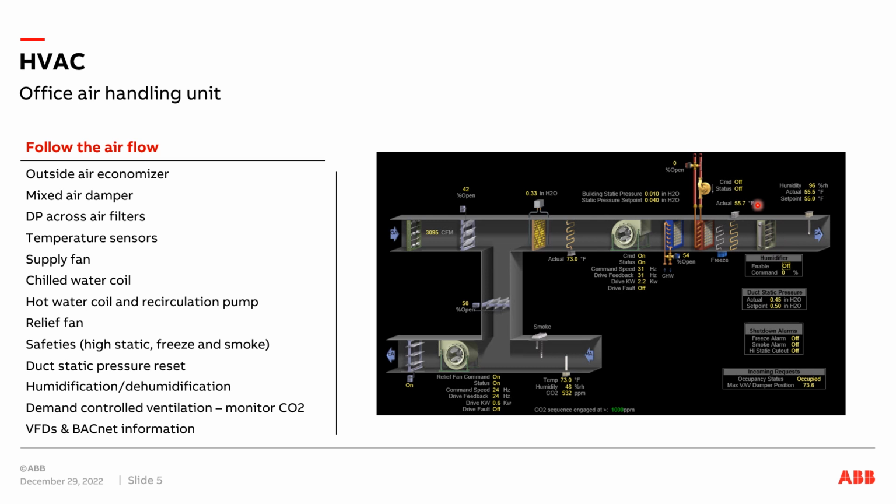And then this last little part here is a symbol for humidity. If the space is too dry, we can add humidification, add humidity to the air to make it more comfortable. On production floor units, something where you're building electronics in Wisconsin winters where it has the potential to get dry, you can believe static electricity is not good when it comes to electronic assembly. So we make sure that we keep the production side very humidified, high levels of humidity to make sure you don't get those static shocks. So that's another little part of the HVAC system, the humidity levels.